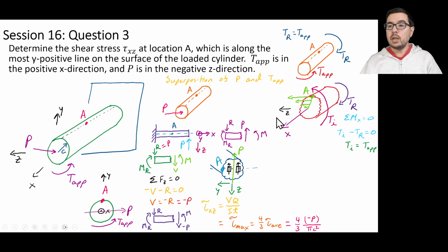And we see that these stresses are acting in the z direction. You see that, right? This was z over here, and so the way we've sliced things, it's acting in the z direction. And which face is it? It's on the x face. So it's going to be a tau xz shear stress. And x is coming out this way, so that's a positive, and it's positive in the z direction. So tau xz is going to be positive.